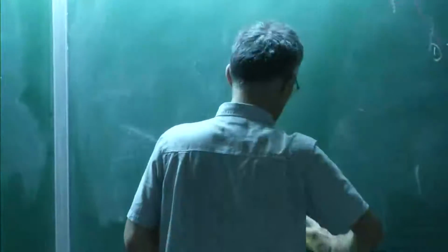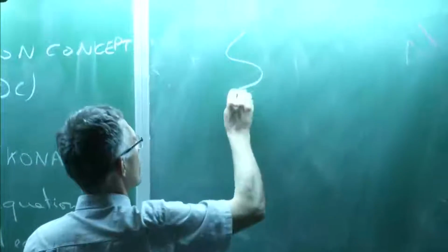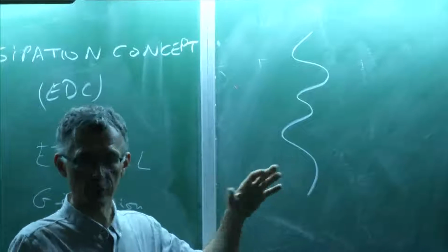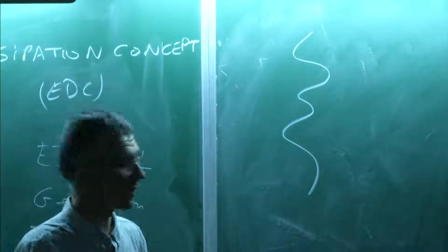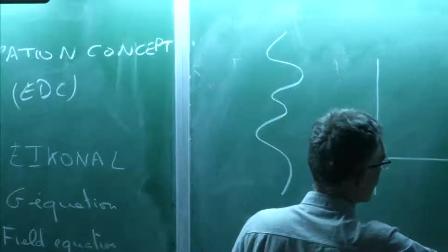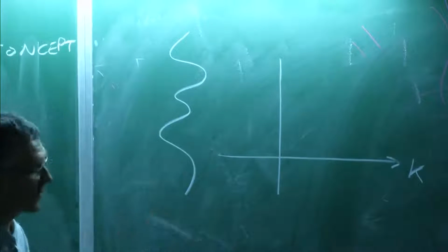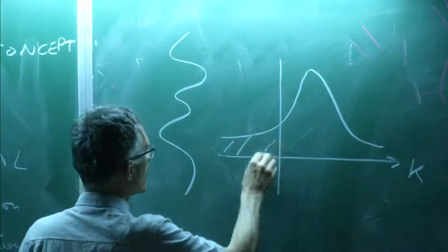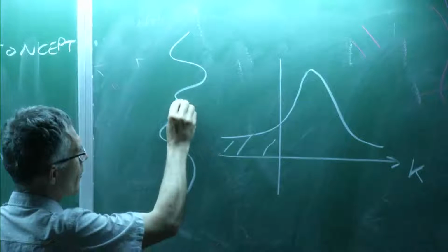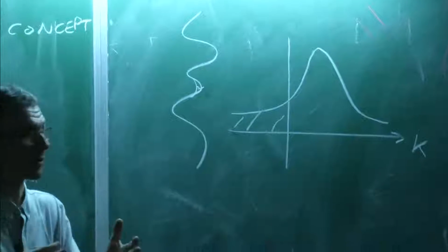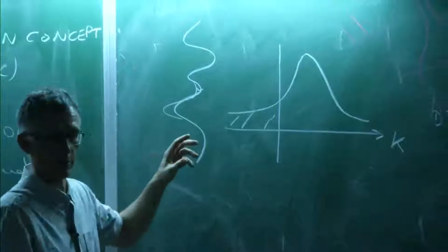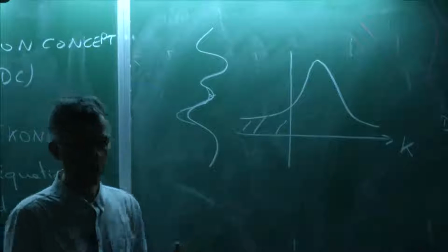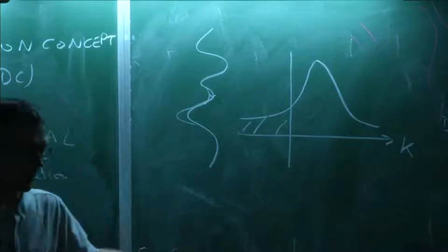That's another thing which has been done quite often. If there is a flame like this, that's the flame front. Certain parts of this flame front are stretched, but certain parts are compressed. And the very interesting thing is that when you do the PDF of stretch on a flame like this using DNS, you find something like this. You find that there are places here which are compressed. So this point, for example, maybe will have less surface a few milliseconds later, and this point will have more. But on average, there will be a little bit more stretched than compressed, because otherwise the surface would not grow.